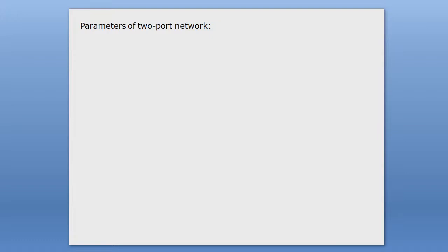What term do you generally keep constant to draw these characteristics? The base current, IB. You consider collector current and collector to emitter voltage as variables and base current as a parameter, because this base current is fixed for a particular set of collector currents for different values of collector to emitter voltage.